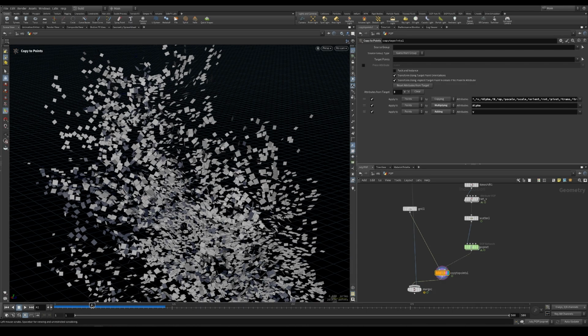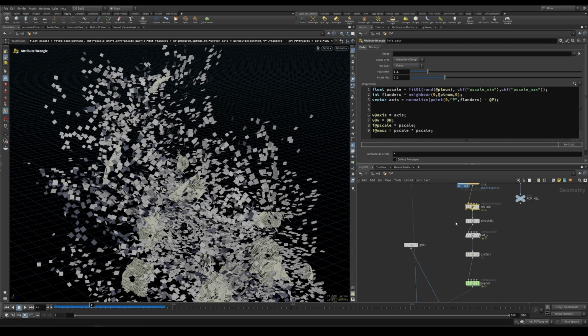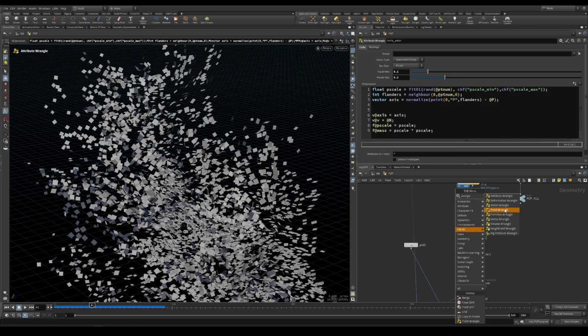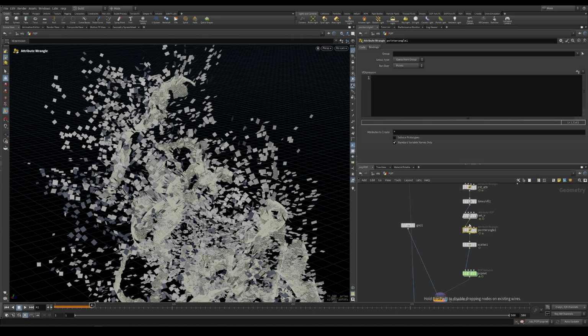So we need to introduce something called the angular velocity, which is expressed as w. It's a vector like the velocity, so not normalized. But the problem is, even if, let's take a point wrangle before the scatter, even if we set this angular velocity, so @w set, I don't know, 4, 6, 1, it should be computed by default by Houdini.